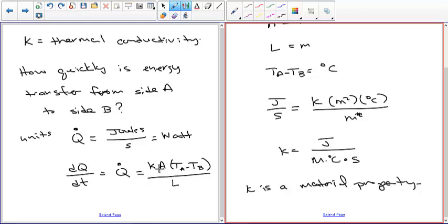So the temperature difference between the air and the fin is larger than if you didn't have the fan running. Instead of having those hot air molecules hanging around and not helping your heat transfer, you blow air past them and you create increased heat transfer.